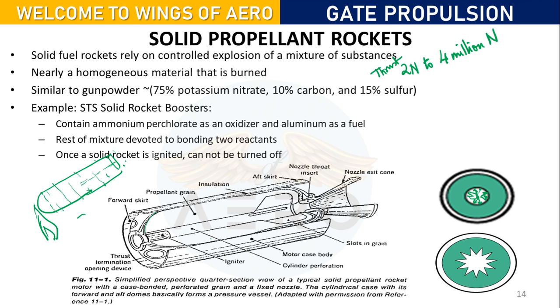And if I talk about the cooling system, a lot of cooling systems are used. First of all, they use ceramic liners, then thermal coatings. They use high temperature materials, and film cooling is used. That kind of cooling system is used for solid propellant rocket motors.